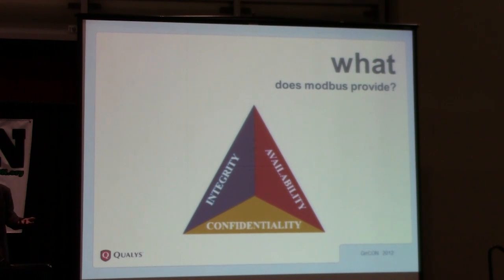Secondly, no authorization. If there is no authentication, there cannot be authorization. Authorization is basically, okay, I agree that you are who you claim to be, but are you authorized to do it? Are you authorized to do a read as well as write, or just read? So there was no confidentiality. There was very little integrity. So a man-in-the-middle attack could easily be possible. So we said, okay, Modbus was a pretty old protocol, as many of you who raised your hands know, maybe a 30 year old protocol.